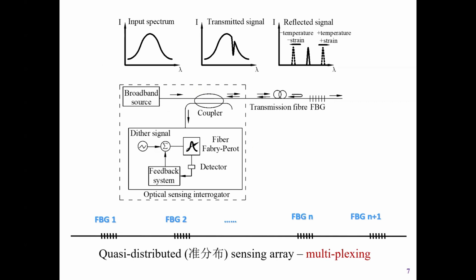And one feature of multiplexed measurement is one fiber line. What we call quasi-distributed sensor technology is one fiber line. We can have multiple gratings, and so multiple points for measuring strain and temperature, with just one fiber line. This is totally different from conventional technology, like electrical resistance strain gauges or vibrating wire strain gauges.